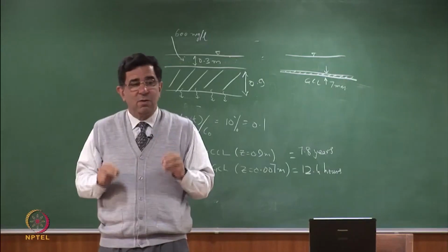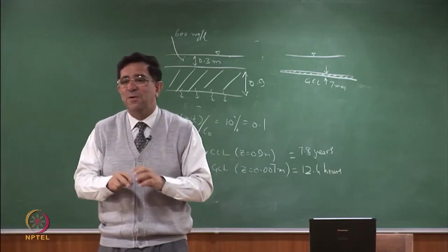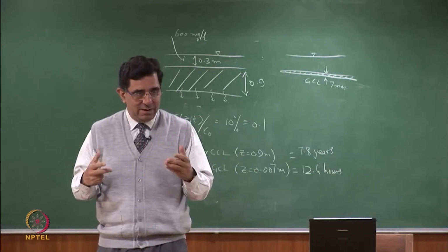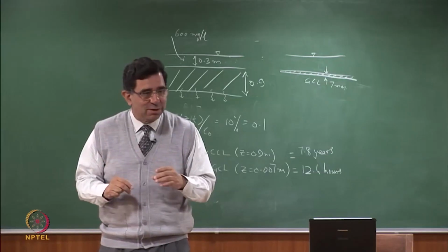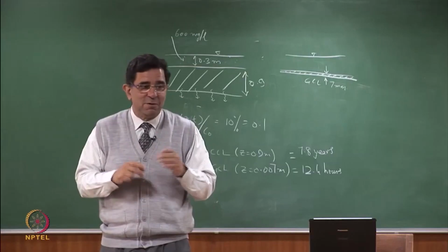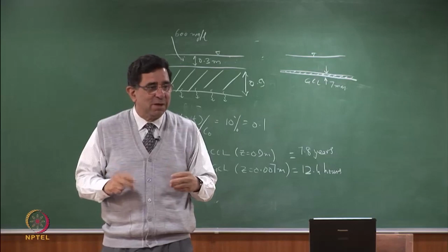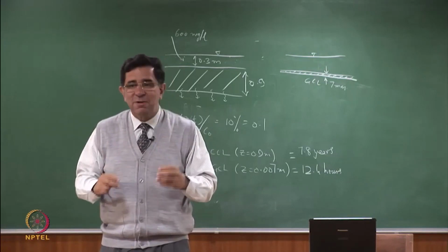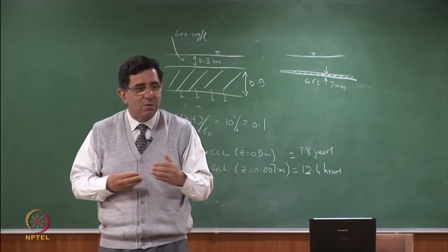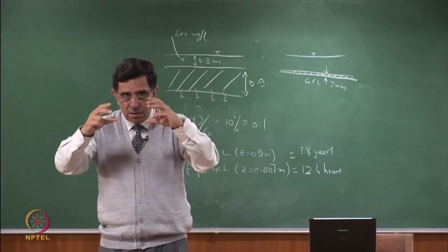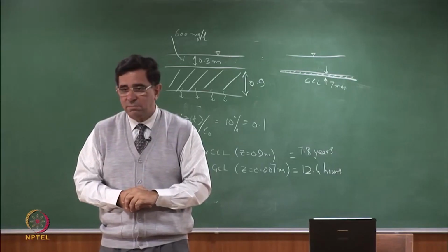Still, I'm saying both advective and diffusive have been treated separately here, very, very simplified. Actually, it will be much more different. The compacted clay liner will not be saturated. So the saturated permeability will not operate till the wetting front moves through it. We have used a saturated permeability, steady state condition. Same thing will happen through diffusion. So we have simplified the problem so that we get at least an idea of what is happening as the leachate passes through the barrier layer at the bottom.